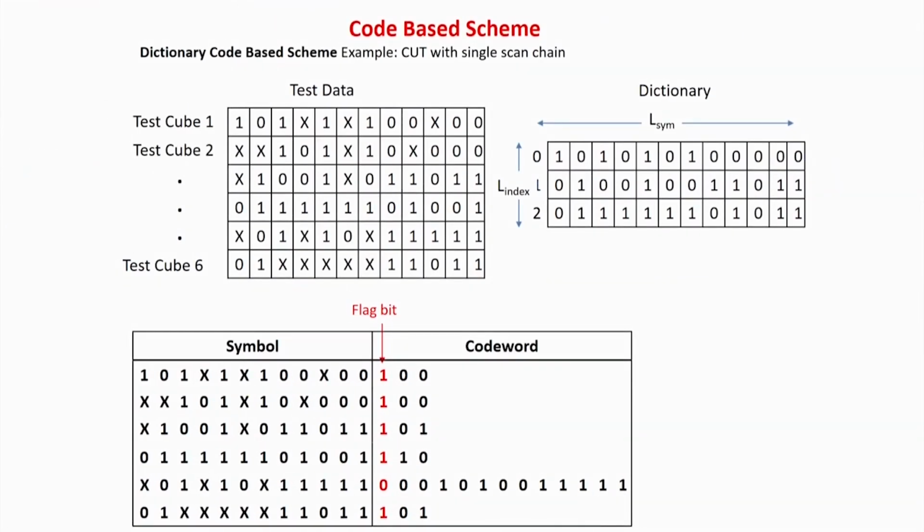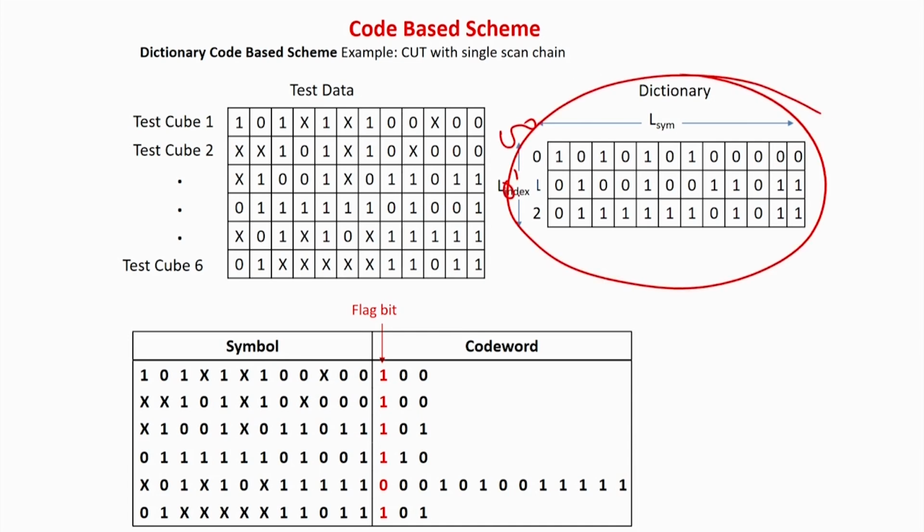Very simple idea. Now the question is how can I design this circuit? So your input is 0 0, 0 1, 1 0, and outputs are this many. So very simple Karnaugh map you can optimize, 2 variable Karnaugh map. How many outputs will be there? 1 2 3 4 5 6 7 8 9 10 11 12. So 12 Karnaugh maps I have to solve, and I can get a digital circuit, and I will get this. Very simple. Problem, it is going to be a very large implementation.